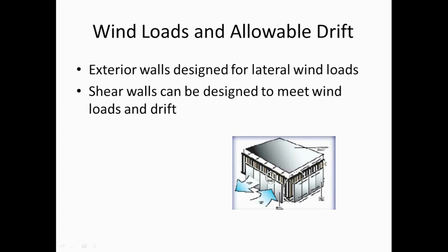If you look at this simple drawing down here, where you have the wind loads normal to that exterior wall, this wall goes into bending, taking care of the wind load, plus it's carrying the dead load of the structure from above. So that's combined stresses. Over on this side, where the wall is parallel to the direction of the wind, it